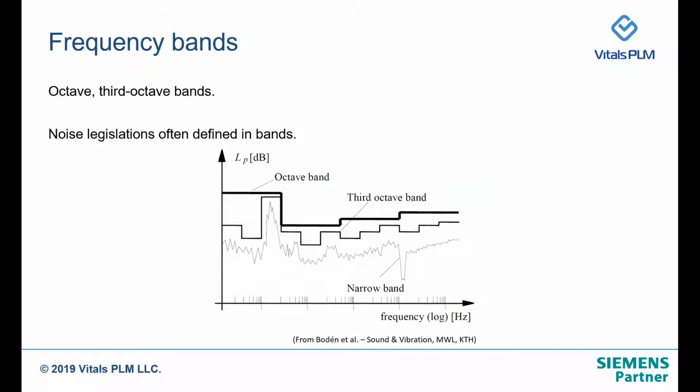And in that case, converting the narrowband or broadband into bands can help to normalize the energy content in the narrowband and broadband, and that will help us to take out the dependency on the resolution which is coming out of the time sampling length taken for calculating these spectra.